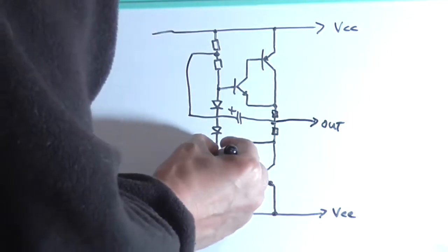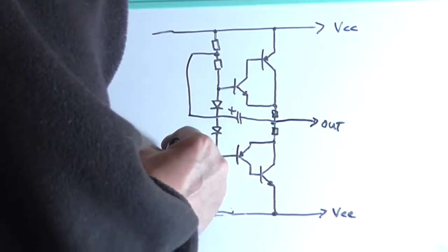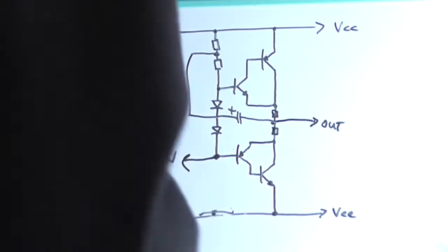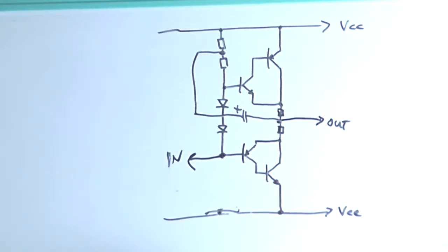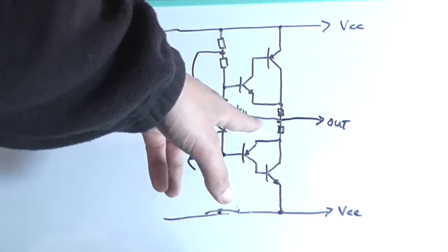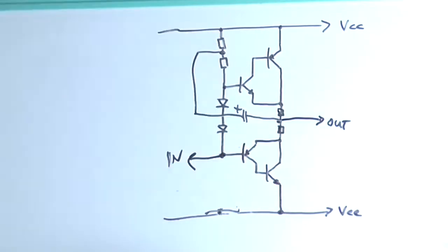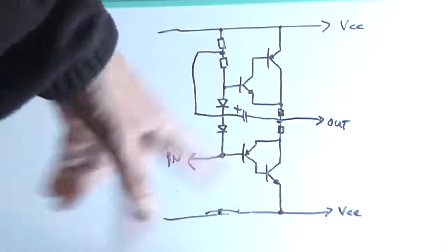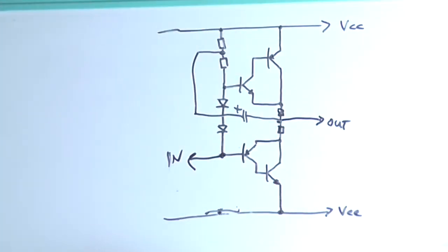I'm going to test this output stage. That's supposed to be an N. Oh dear. Yeah, there we go. I'm going to basically test this output stage without the capacitor first, and I reckon around about a 100 microamps should be about right. But first, before we worry about that capacitor, we'll get the thing biased and look at it on an oscilloscope, and feed an input signal in here and look at its output with no negative feedback or global feedback before we look at the input stage that's going to be connected to it.